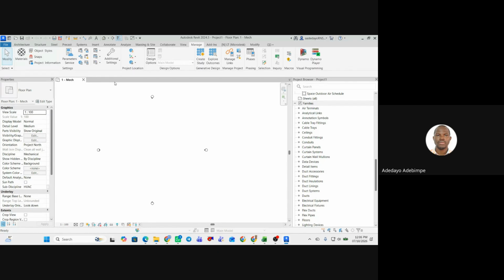You understand? So if they have given you a base point coordinate system and all those things, you can acquire the coordinates that are in the architectural model and use them, so your project will now be in that location, because everything you are seeing in Revit is the real world coordinate system that they have modeled in Revit. I don't know if you understand what I'm saying. Online people, did you get what I'm saying? So they model the real world coordinate system in Revit.